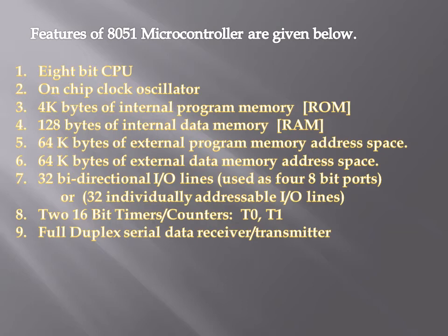Moving to the data memory, it has a RAM of 128 bytes, but has the capacity of connecting 64 kilobytes of external program memory as well as 64 kilobytes of external data memory. Then it has 32 bidirectional I/O lines, or I/O pins, used as four ports, four 8-bit ports.